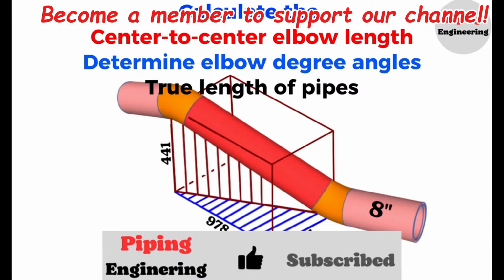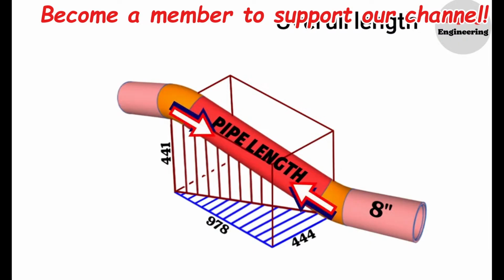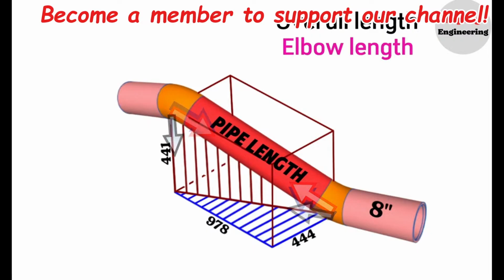Alright, let's dive into today's lesson. To determine the length of a pipe section between two elbows in a pipeline, we will follow these steps. Calculate the overall length and the center-to-center distance between the two elbows. Determine the angle, length of the elbows, and their takeoff dimensions. Finally, subtract the elbow lengths and welding gaps from the overall length.